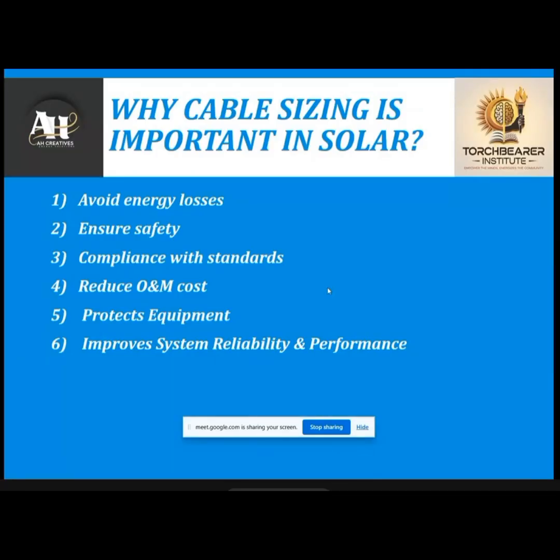Definitely, it ensures the safety of the equipment, because if the cable is not properly sized, it may heat up and burn for some reason, like the heating effect of other cables installed near the cables, or other factors like the grounding factors.